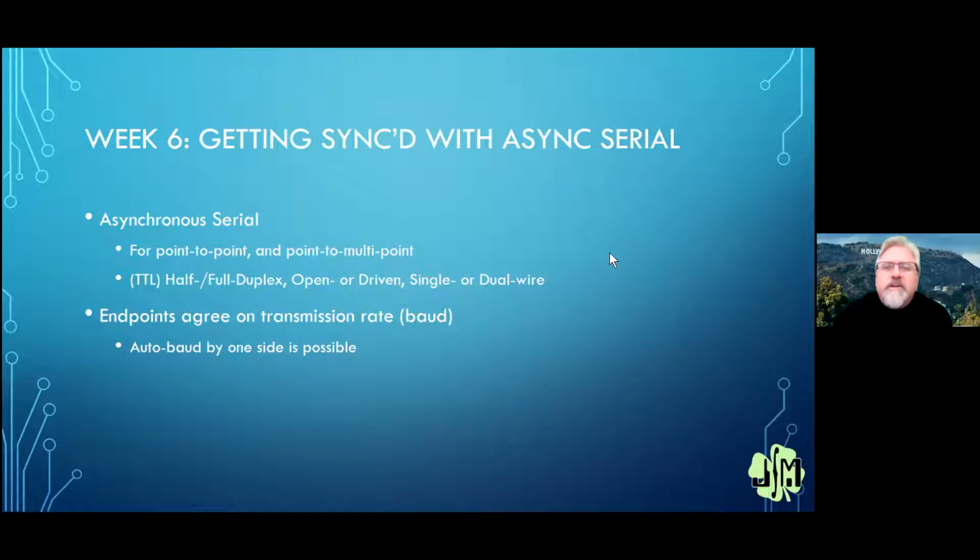Anyway, with serial, we're going to do half and full duplex. Half duplex is one side at a time talks. Full duplex means both sides can be talking simultaneously. We can send data while receiving data. Now, with the P2, we have lots of opportunities for generating and receiving serial data, and some apply to both. As far as half and full duplex, some are not so good for the other.